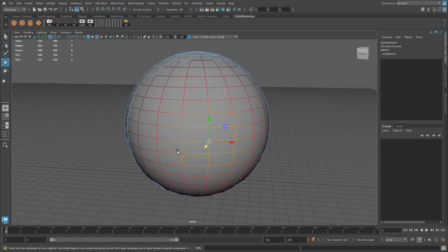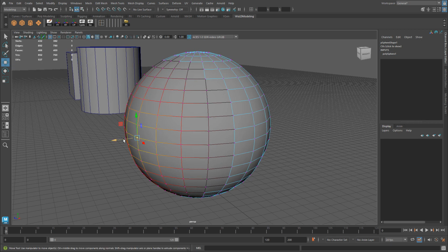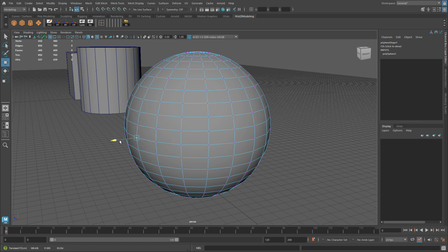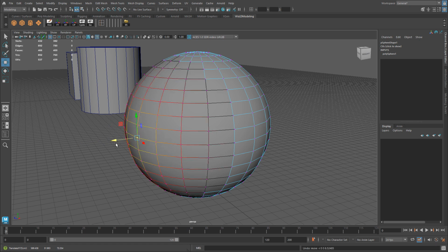And what soft selection does, it creates a soft radius, a fall off effect from your selection. So then you can modify your object at a more gradual level. So this is why you have a soft selection being made around a single vertex, and then it has a small fall off radius that will pull the other components along with it. So this is very helpful if you want to modify an object with a more fall off effect, a softer transition, rather than just pulling one vertex at a time like so. But the shortcut key is B, and this toggles the soft selection mode.